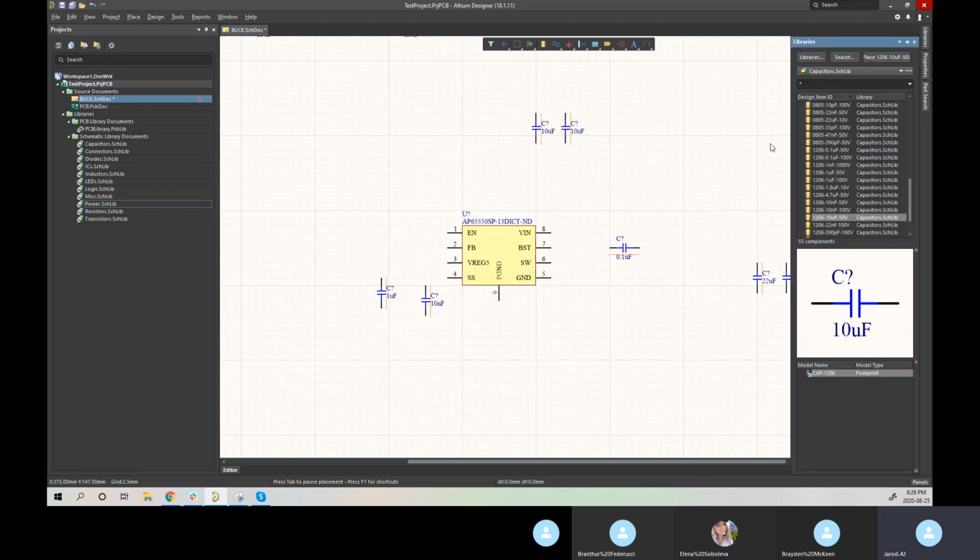The capacitors we need in our design, and then we'll head off to resistors, and then again, same thing. We don't want overspecced parts just for the sake of dealing with them. We typically don't have voltage limits, but rather power limits, which for most designs we don't have a concern about. Most of these are rated 1/8 watt to 1/4 watt, and in most applications that's fine.